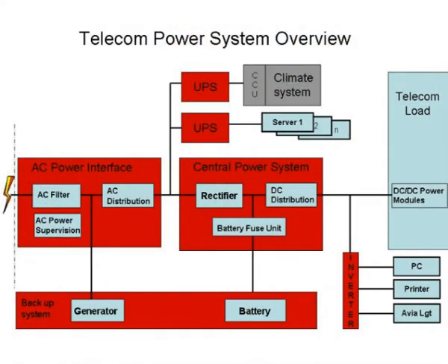Most of the power supplied to the telecom equipment dissipates as heat. So, the switching equipment and the battery banks need to be maintained within a set temperature band for optimum performance and longer life. We achieve this with the climate control system. This mainly consists of air conditioners, temperature sensors, and a control unit. Though telecom equipment can work in a wide temperature range, preferred room temperature set by operators is between 23 to 30 degrees Celsius.